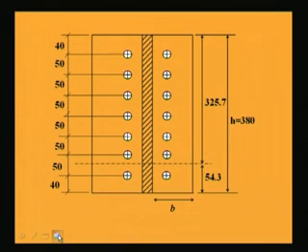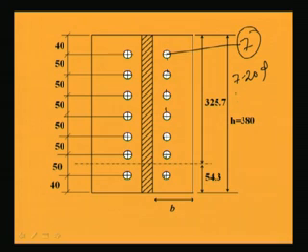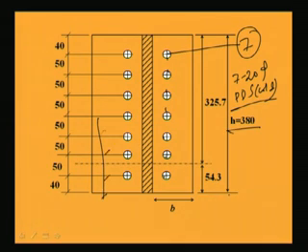So, now we can make the diagram that we need 7 number of rivets. So, 1, 2, 3, 4, 5, 6, 7, 7 number of rivets have been used, and 7 number of 25 power driven shop rivets, cold, have been used, where the total depth will become 380 mm, and the distance between rivets and edge distance has been given in this, that is 50 mm, 40 mm and so on. So, in this way you can make it.